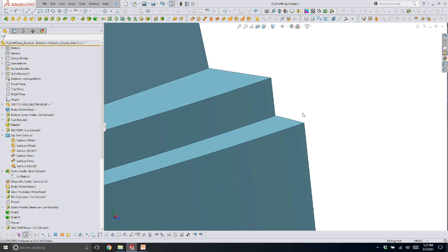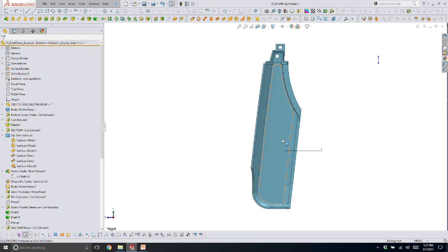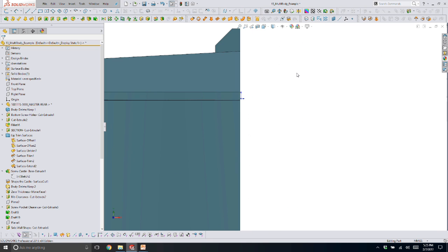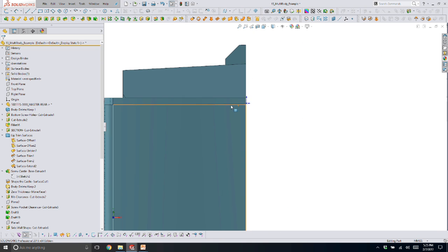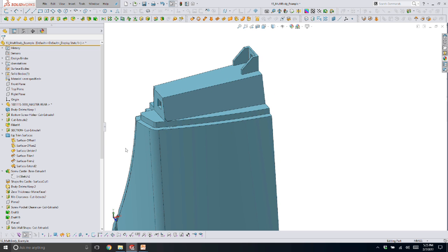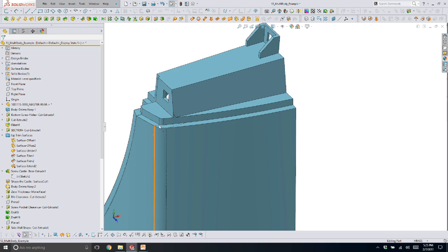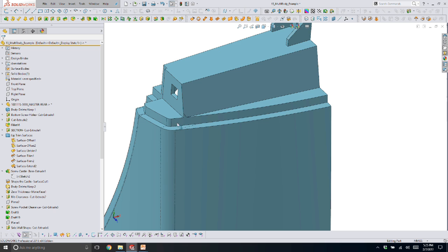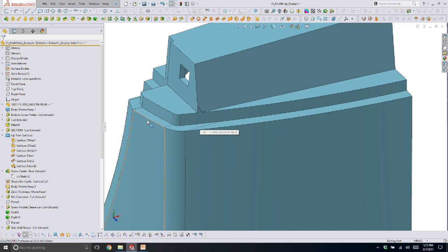through there, and I'm going to have a nice straight edge when the opposite half of this part's not going to look like that. We're going to be nice and straight through here, and you can see that extra material that was added. So you can always draft an entire perimeter. If the feature fails, just go back, look at your little yellow arrows, make sure that they're pointing in the right direction, selecting the right face, and that you've picked the entire chain.